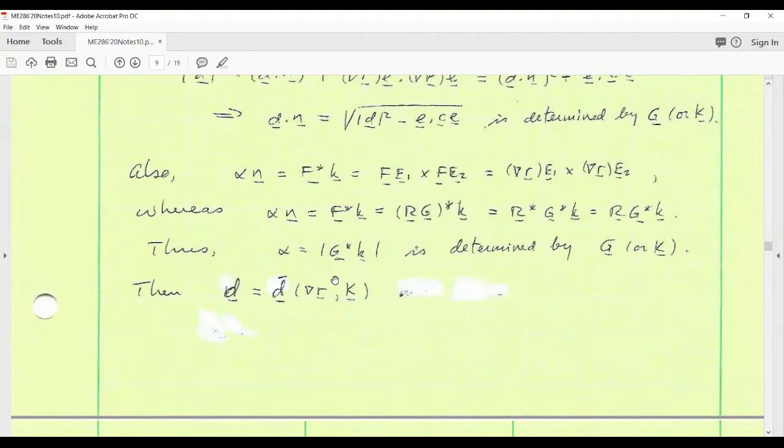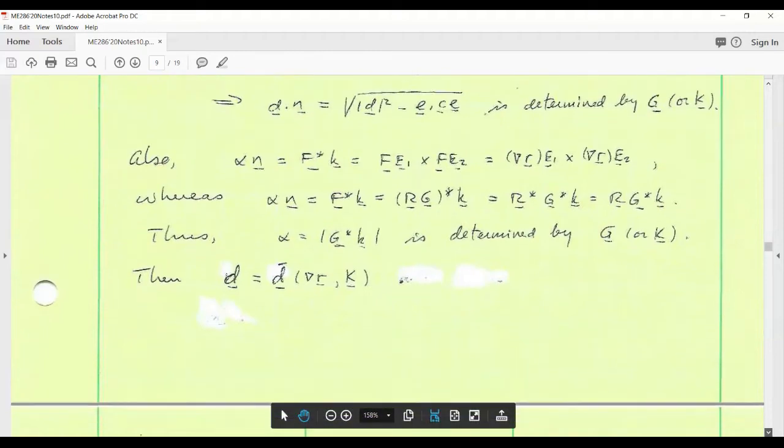And so if we continue to pursue this procedure, then we have to deal with those additional variables. And last time we ended by showing how the first director, D, which is the midplane value of the through thickness derivative of the 3D deformation, can actually be solved in terms of the two-dimensional gradient of midplane deformation, grad R, and the plastic deformation at the midplane. We're assuming here that this has been frozen at a forward integrated value of the flow rule. We freeze the plastic deformation in the body and then minimize the energy with respect to deformation, and then continue the process as long as we want. Forward integrate the flow rule again and repeat.